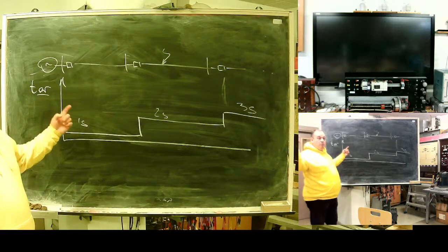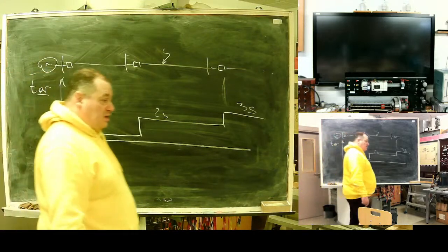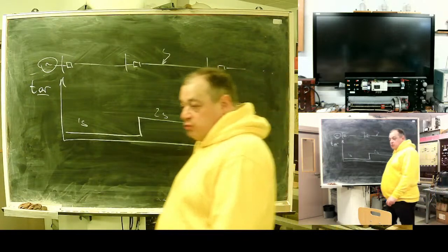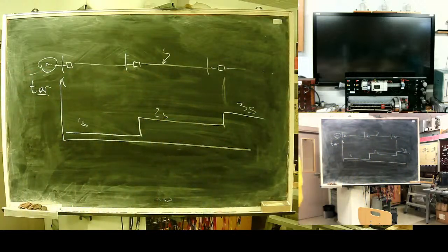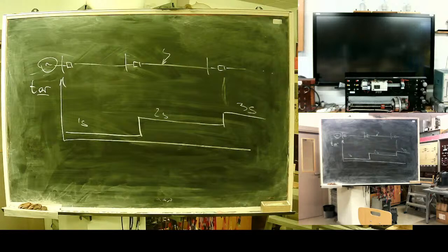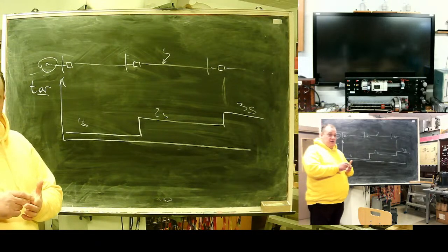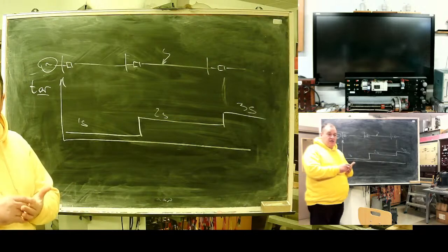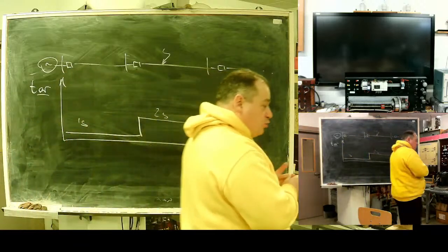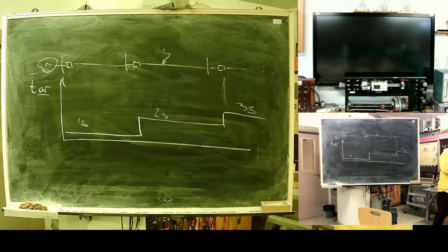If we have power from both sides, it will be a tricky one. It's more complex reclosing. Okay, so the idea is how auto reclosing should operate. It should switch the line back after a time delay if the line was disconnected by protection. Manual operation should not trigger auto reclosing. And another one, it should operate a limited number of times.